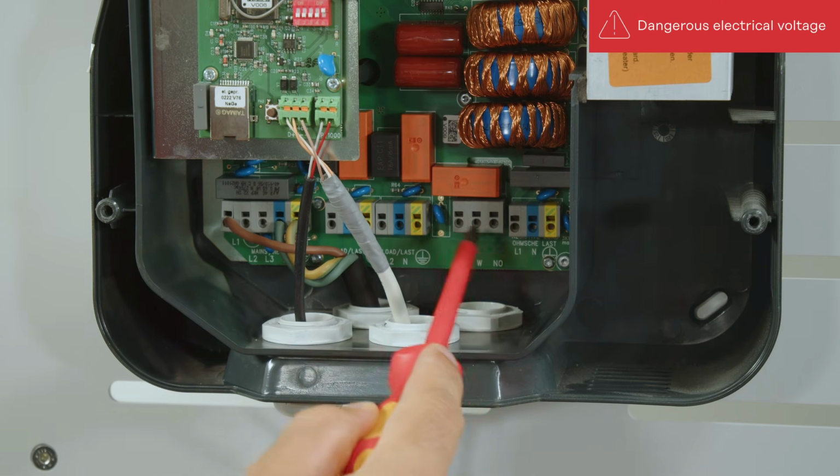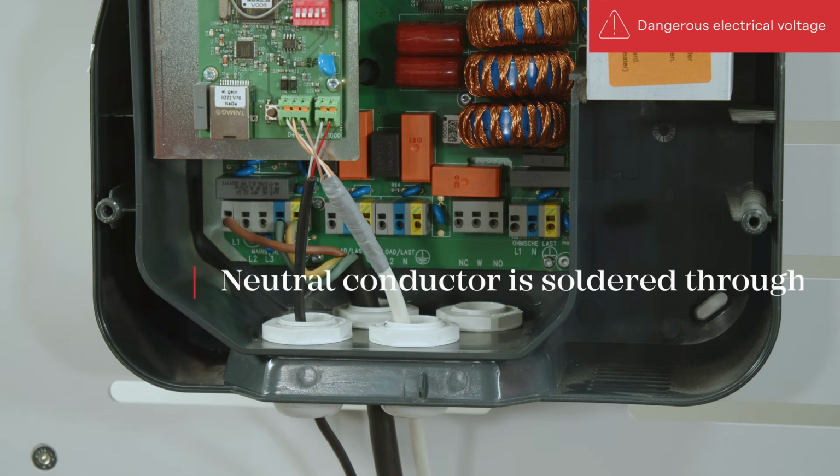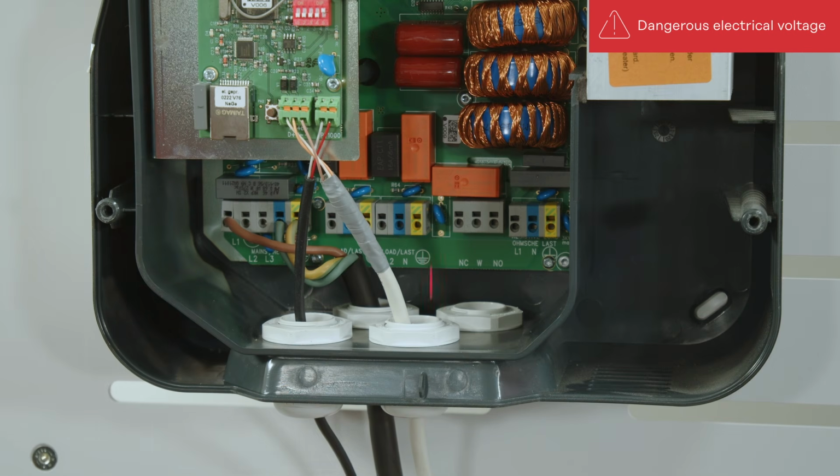In blue you see the neutral conductor connection points. Please note they are bridged internally. So not each phase needs to be connected separately. You only need one neutral conductor connection per heating rod.